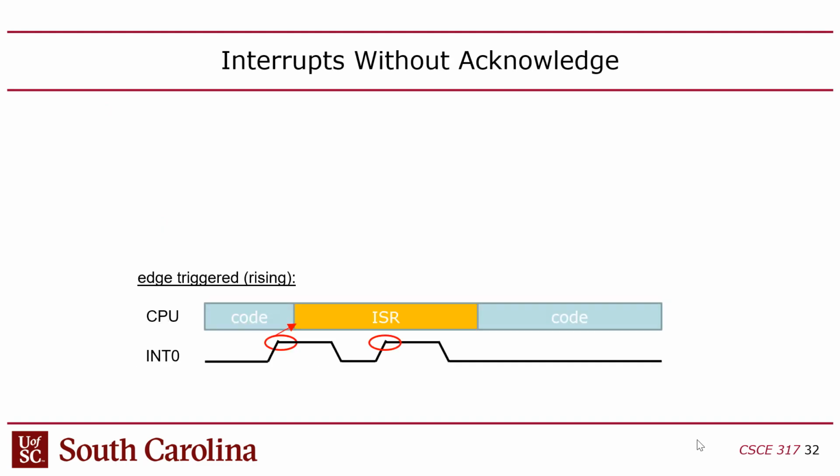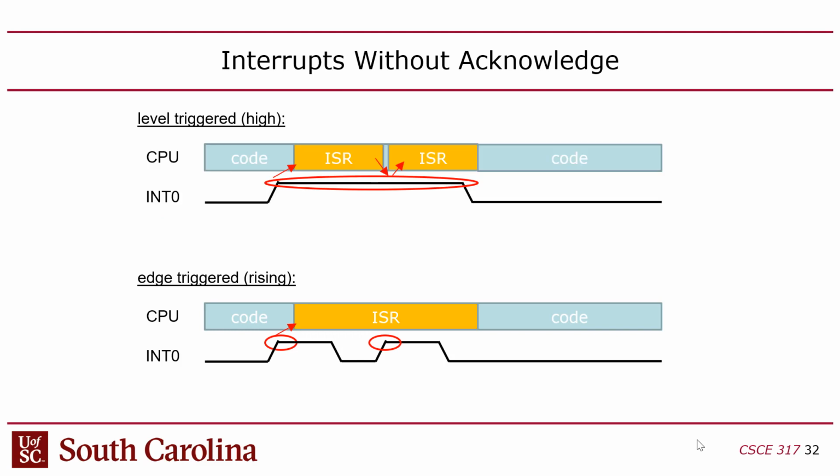Right, so about the interrupts. We talked about 2 ways to do interrupts, level triggered and edge triggered. So basically the idea is that the peripheral has a wire that goes back to the CPU, a single bit wire. And it gets the CPU's attention by changing the value on that wire. The CPU could respond to the level being high on that wire, or it could be edge triggered, where the CPU is looking for a transition from low to high or from high to low, right?